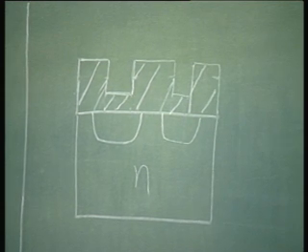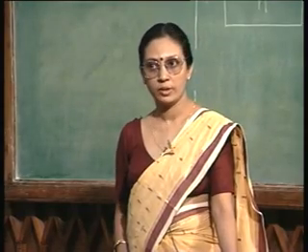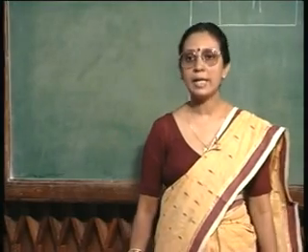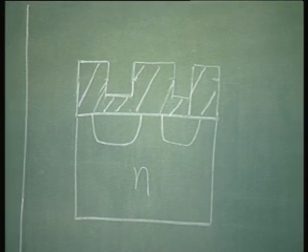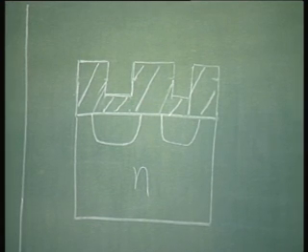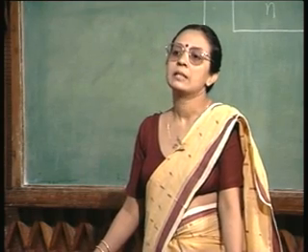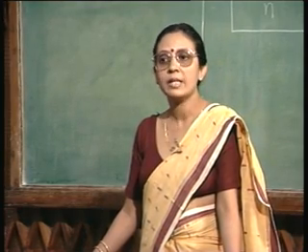Can this oxide serve as the gate oxide of the MOSFET? The answer is no, it cannot. There are various reasons why this oxide, the thick field oxide which is already present here, cannot serve as the gate oxide. The first reason being that the thickness of this field oxide is very high.